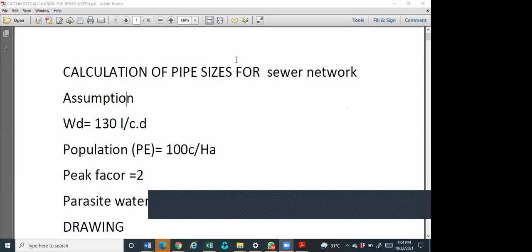Even in Germany today, in places like Hamburg, the water demand is about 116 liters per capita per day. Places like Munich and Stuttgart, down south, are still using 120. So the average water demand per capita per day in Europe is about 120. It's when you go to America and Canada that you see it going up. For the UK, I guess it should be between 100 and 150, which is also the WHO recommendation.